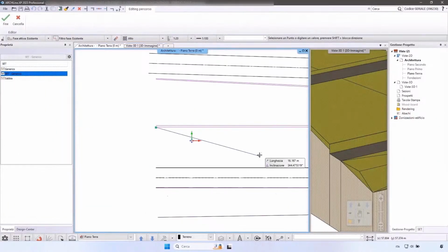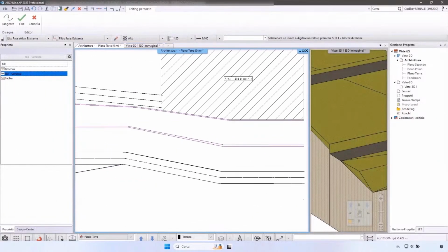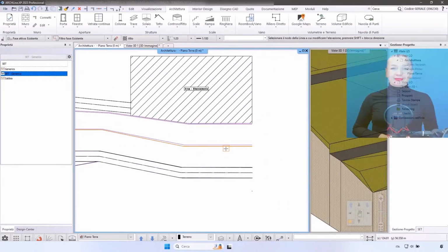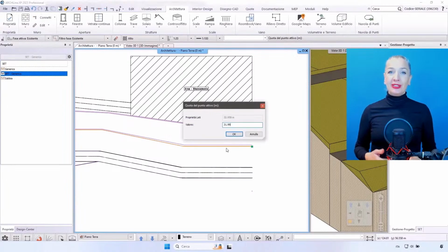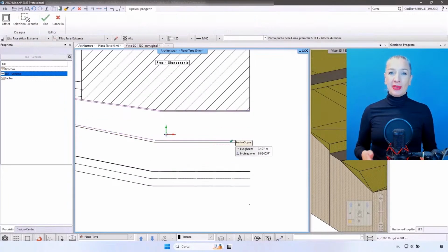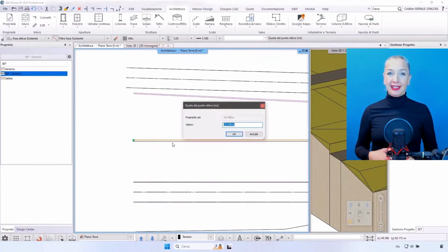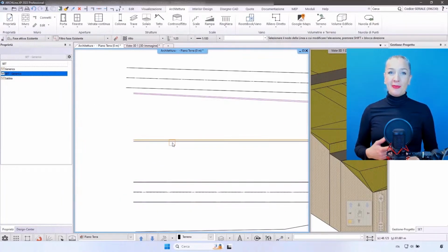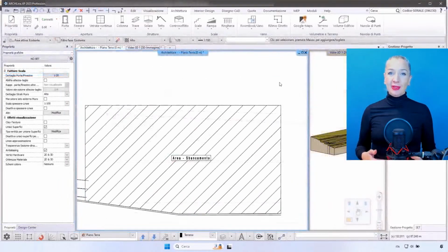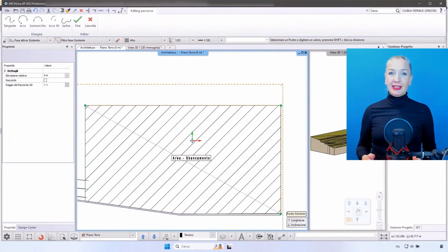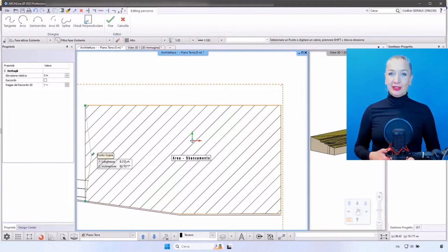Terrain has its specific tools for modeling roads by tracing the road path. The program cuts the road into the terrain, or completes and fills in the missing areas according to the road height. A plateau is required when topography is added to the 3D model because it cuts through the terrain where a floor is not able to.